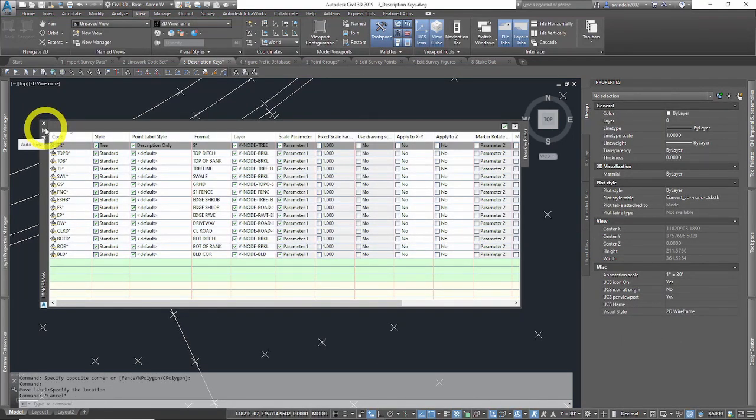The last thing it wants us to change in just these tree description codes is the format on all of them. If I'm reading it correctly, we're going to change the format to $1 inch, and these are pretty tricky. The $ is a special code that tells Civil 3D we want to use only part of the raw description in the full description, so it's plucking that $, plucking one space out of here. So that's all we want. It's adding a 1 in front of it.